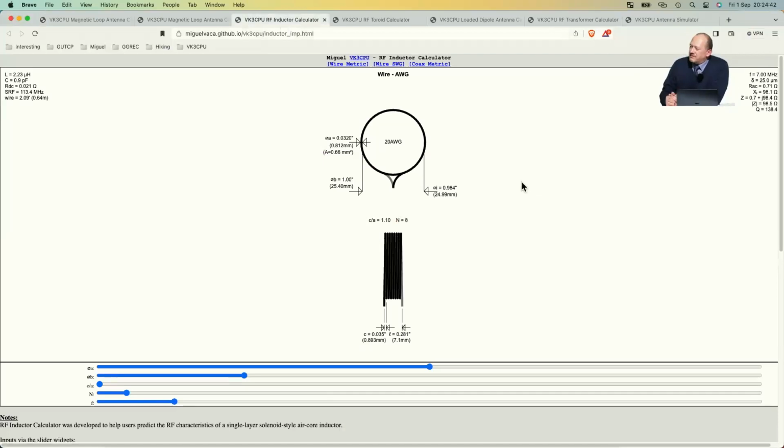Generally, the rule of thumb they say with mag loops is that you keep it 2 diameters away from the ground. Have you heard differently? Anyone else? No? Yeah, but no, it doesn't simulate. It's not an electromagnetic modeler. But the idea is if you do measure your antenna characteristics, you can feed that back in because you can measure effective bandwidth, and then you can slide the RE setting until the predictions match what you've measured, and that'll tell you your effective loss resistance of the system.